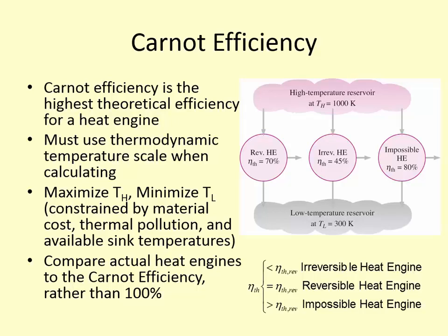And then we also have to be concerned about thermal pollution and things like that. And then similarly with a low temperature reservoir, in many cases we're using the environment as our reservoir, and there's limitations on that simply because the temperature outside is what it is. We can't artificially reduce that temperature without putting in work, in which case we're adding more work to our system, which we won't get any additional benefit out of just by trying to increase the efficiency of our heat engine.